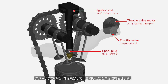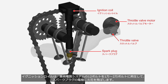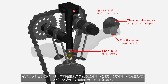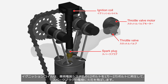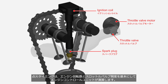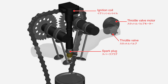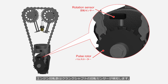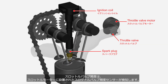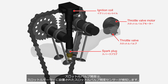When the spark plug sparks, the compressed air-fuel mixture ignites. The ignition coil steps up the 12 volts from the vehicle's electrical system to 10,000 to 20,000 volts, creating a spark at the spark plug electrodes. The basic ignition timing is calculated by the engine control unit based on the engine speed and throttle valve opening. The engine speed is detected by the crankshaft rotation sensor, and the throttle valve opening is detected by the throttle valve position sensor installed on the throttle valve motor.